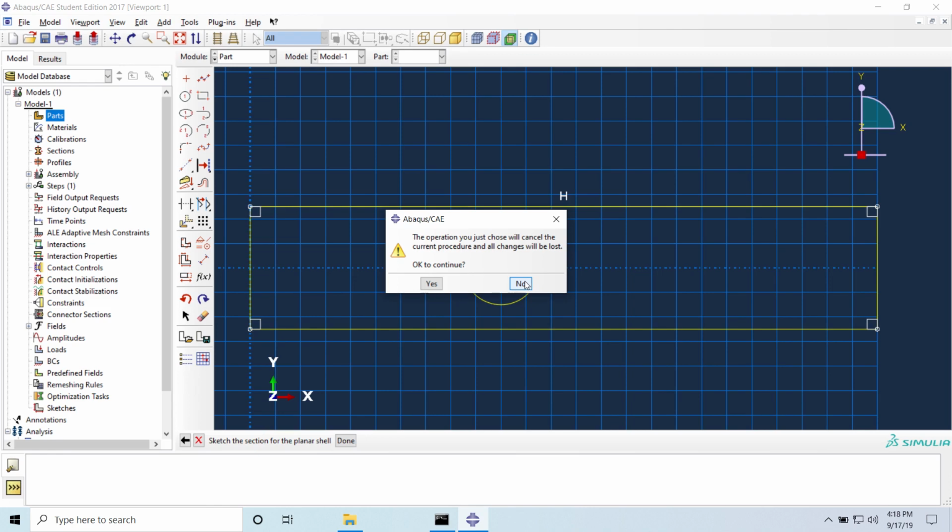It doesn't matter. The only thing that is gonna change if you draw your beam here or here are the coordinates of your node. But the stresses and the solution of the displacements, everything is gonna be the same. The way we force the solution, does it affect it? It doesn't affect it. It only changes the input file, because now your node 1 is not gonna be here, but here. But in terms of the solution, it's gonna be the same.